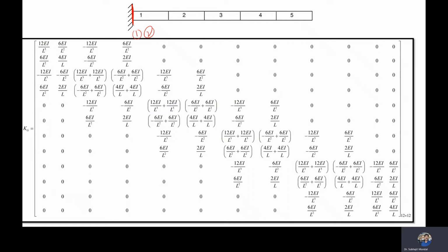Now if we add some value to the diagonal term, so that stiffness become high, that basically can replicate the fixed boundary conditions. If we add some value in such a way that this term become very high in comparison to other off diagonal terms or other diagonal terms.